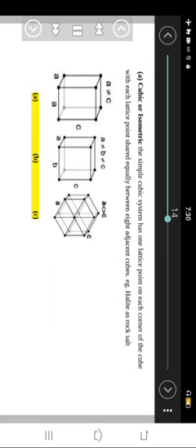Figure 7. A, cubic. B, tetragonal. C, orthorhombic. D, hexagonal. E, monoclinic. F, triclinic. B, tetragonal crystal lattices result from stretching a cubic lattice along one lattice vector, making the cube a rectangular prism with a square base. E.g. zircon. C, orthorhombic lattices are made by stretching a cubic lattice along 2 lattice vectors by 2 factors, forming a rectangular prism with a rectangular base. All 3 bases intersect at 90-degree angles and the 3 lattice vectors are mutually orthogonal.